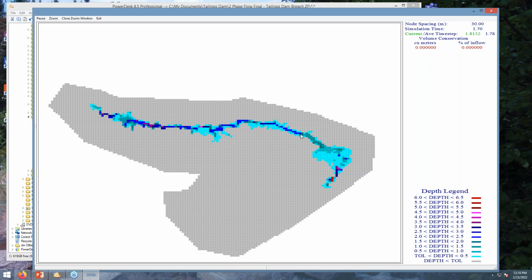The mud flow layer, as the water is drained out of this, is viscous enough that as the water pulls out more sediment and increases the concentration, this will cease flowing. So we get down here to the bottom and it's completely flat and it runs to the outflow element, ponds or whatever down here, because this was following the general line of the channel, even though the channel was not in this model per se. The topography existed for the dry channel more or less, and so it followed the channel down.